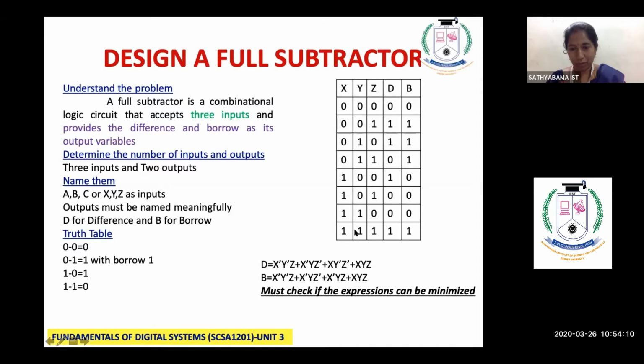Then here also you see 1 minus 1, it will become 0. So again it is 0 minus 1. So I have put a borrow as 1. Then this, again, you have to perform the subtraction and you have put like this. So here also the same step, we have to find the minimized expression for the output variables. Here also you have two output variables. What are they? One is difference and the other one is borrow. So you go to difference and say it in English. Difference is 1 when X equal to 0 and Y equal to 0 and Z equal to 1, or X equal to 0 and Y equal to 1 and Z is equal to 0, likewise. So that's what I have written.